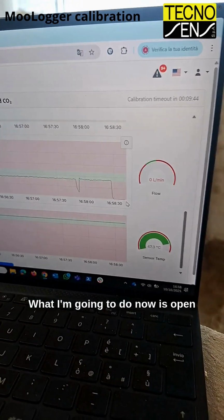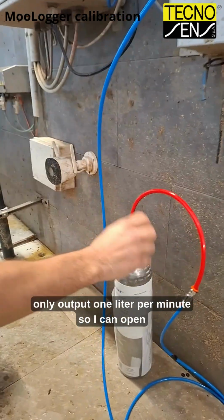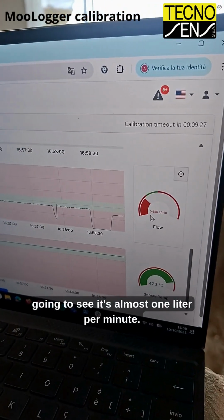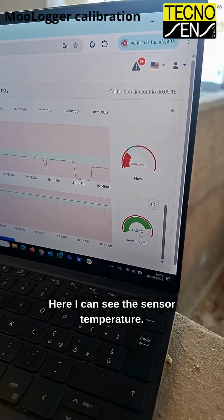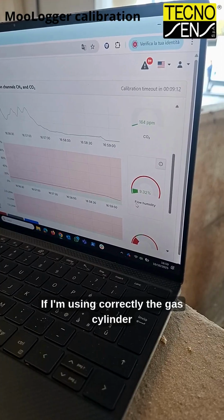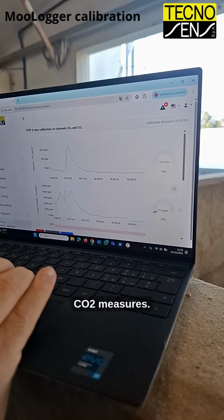What I'm gonna do now is open the gas cylinder from the bottom side here. As this is a fixed pressure regulator, it will only output 1 liter per minute, so I can open all of it. And from the MooLogger web page, I'm gonna see it's almost 1 liter per minute. This one is almost an empty bottle, so that's why it should be a little bit lower. Here I can see the sensor temperature, the flow, and the humidity of the gas. If I'm using correctly the gas cylinder, this value will go lower than 5%. And here I can see CH4 and CO2 measures.